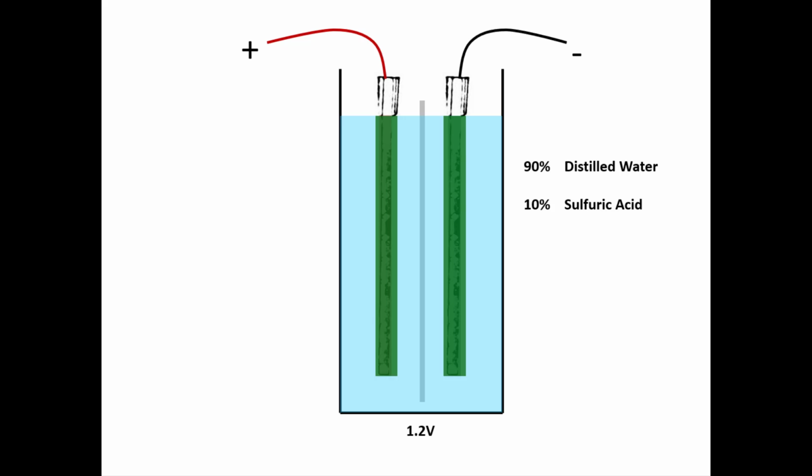The other piece to mention about temperature is that if it gets too warm or too hot, the water could evaporate, leaving us with less distilled water in the battery. So when we were to recharge the battery, the acid couldn't fall back into the solution again for recharge, and that would cause the plates to corrode prematurely and cause battery failure.